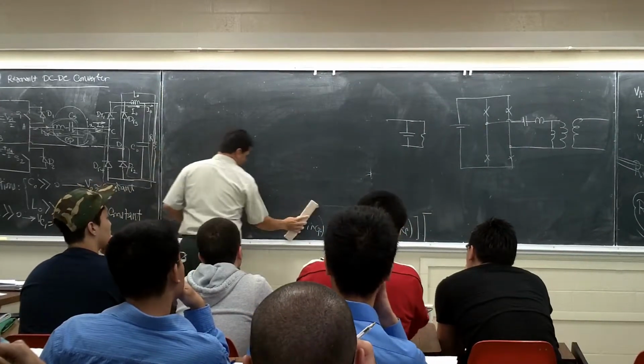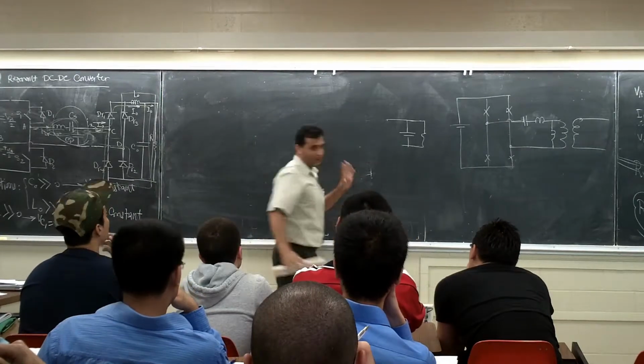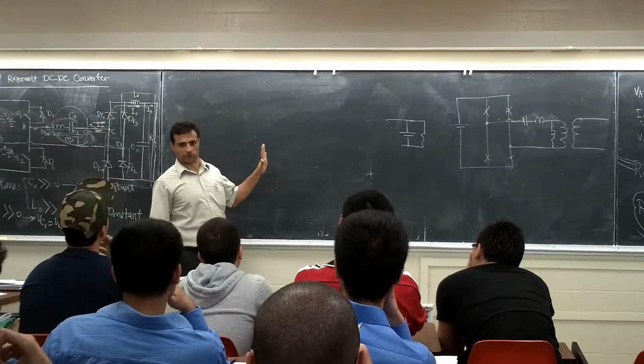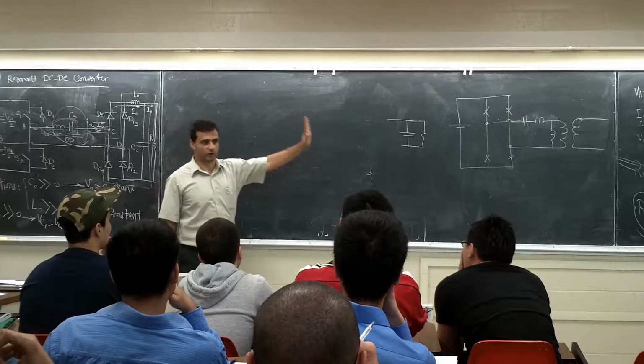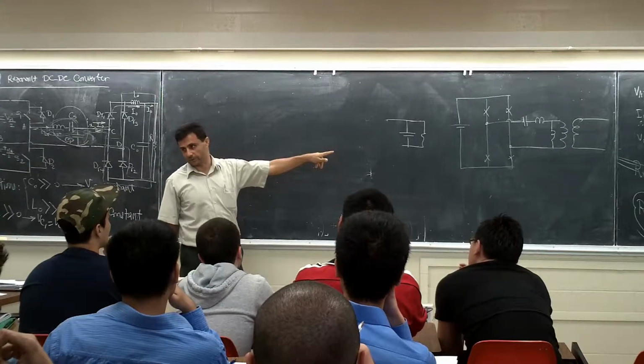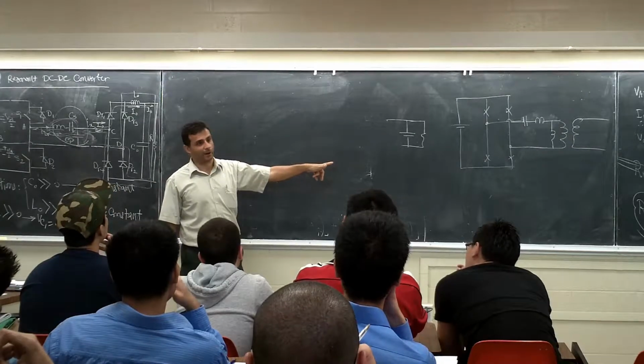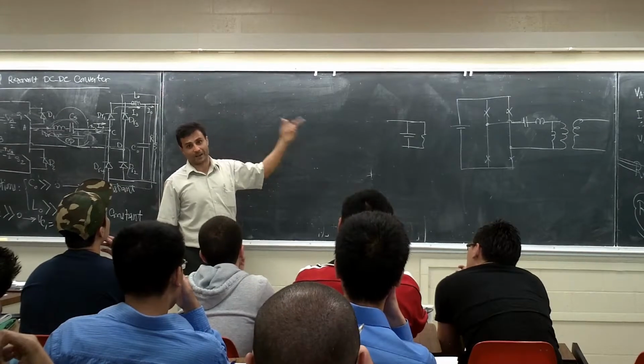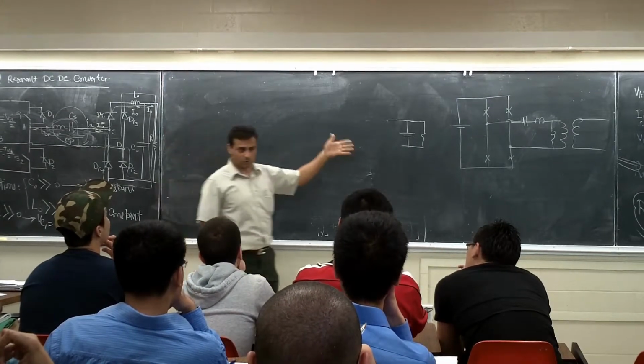And you know the advantage of having them: at least on one side, they do soft switching, right? Either at turn on or turn off. The one we did with the inductive load is going to be at turn on. If you go with the capacitive, it's going to be at turn off. But we usually do it with the inductive.